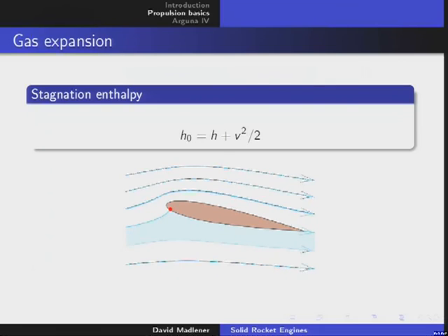Yes, and this stagnation enthalpy is just the inner energy plus PV divided by the mass. And it changes when it's flowing, the enthalpy lowers of the flow. And if it stagnates at one point, for example, this red point here, this is a point where the air does not move. So there's no relative movement between the foil and the air. And a very similar case, for example, for a rocket, when it flows through air, then at the tip of the rocket, there is air on top of the tip that does not move, okay? So at this point, the flow achieves the stagnation enthalpy.